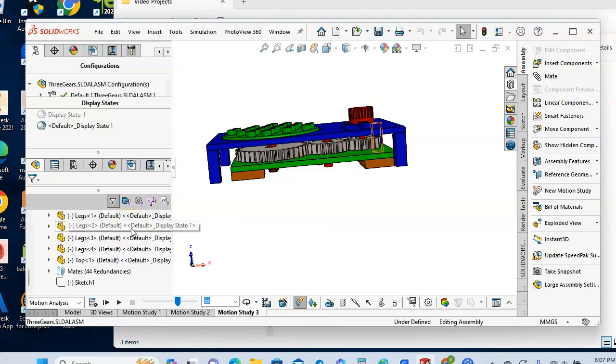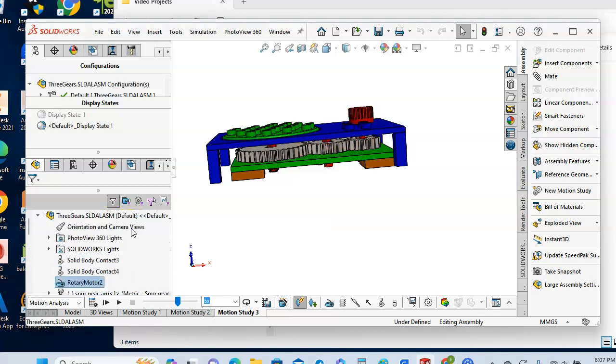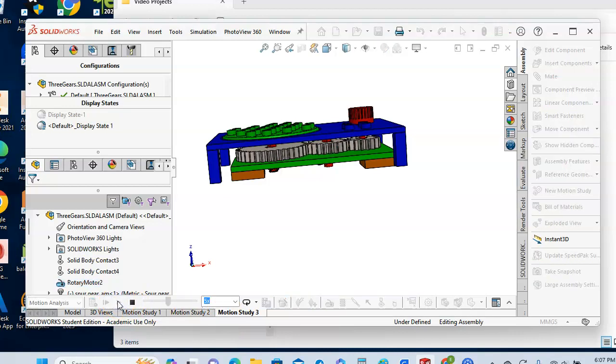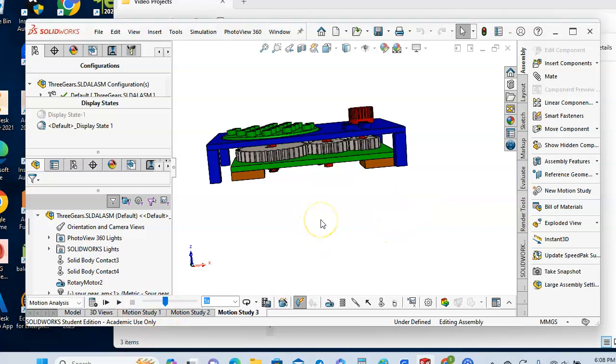But if we run it just in its current state, it doesn't actually work correctly. Nothing really quite seems to be rotating properly. But the step which is missing is that we have to create some rigid groups. And what this particular part of the whole video process is about is to show you how to do that.